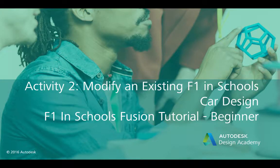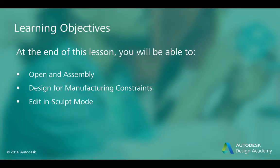Activity 2. Modifying an existing f1inSchools car design. In this activity, you will modify an existing f1inSchools car using the sculpt command and T-splines. You will then be able to use this technique learned to very quickly create your own unique body and wing shapes by modifying the standard Autodesk Fusion 360 f1inSchools car model.